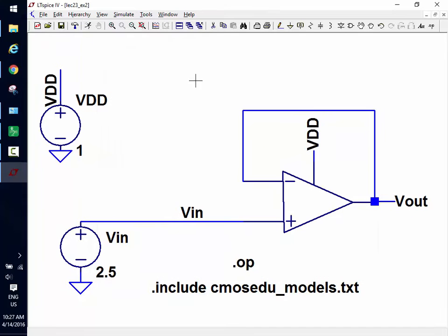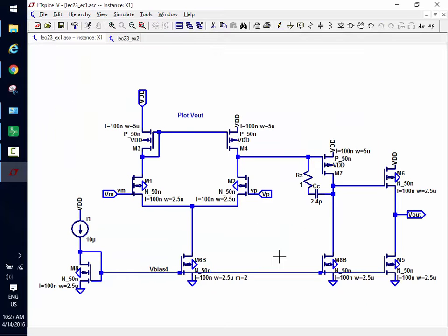And first thing I'm going to check is what's the current being supplied here. Why can't I get the current that's flowing there? No, it's 48 microamps. Does that seem reasonable? Let's find out. This is where you ask, does somebody know what's going on? It's a trivial question. 1, 2, 3, 4. 4 times 10, well, it's going to be a little bit higher, 40 microamps. Is 48 microamps a reasonable value? Yes. Did you see how easy that was?